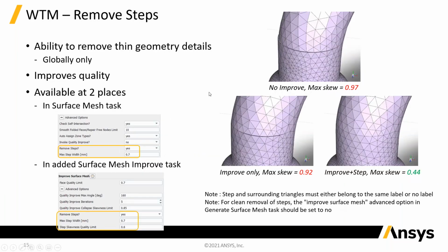This is one that's again really nice. It's akin to removing slithers. So if you bring in a mesh where there's obviously a CAD defect here, it was not intended, but it's a CAD defect, then you're going to have some small, highly skewed cells there.